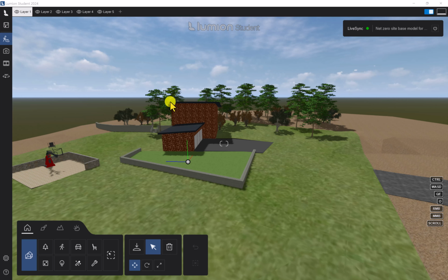First of all, anything which is a hardscape item that follows the contours, which is to say probably a road, maybe a lawn, even possibly a driveway, those things that follow the contour are going to want to stay. Those are typically done by duplicating the toposolid surface, and that's fine. In Revit, you can absolutely isolate those. Even things like paved paths you can do using that same technique in Revit.